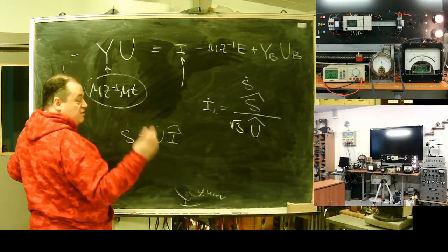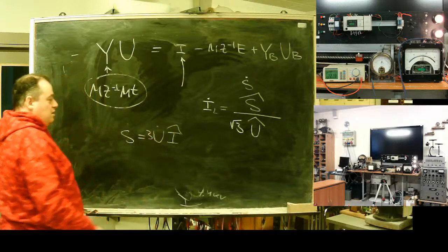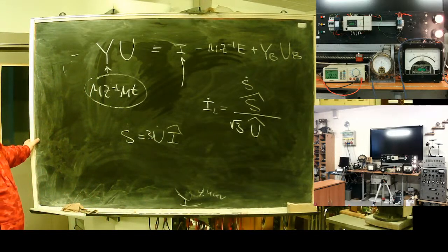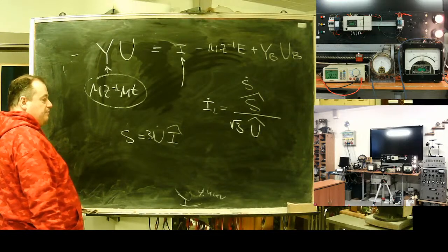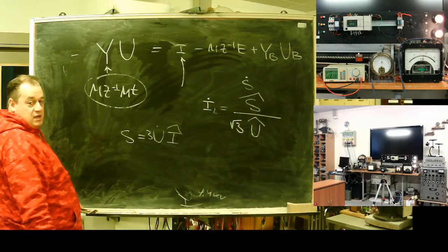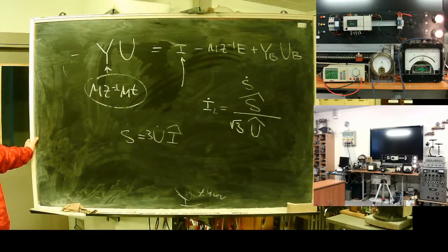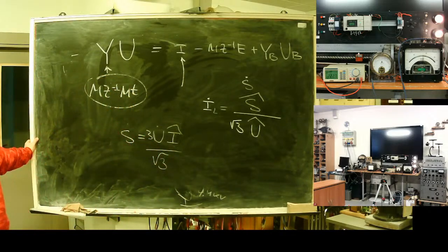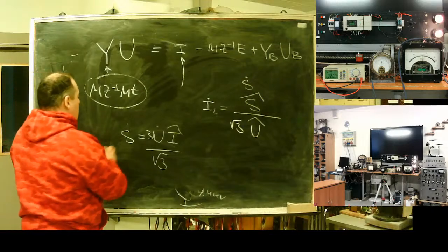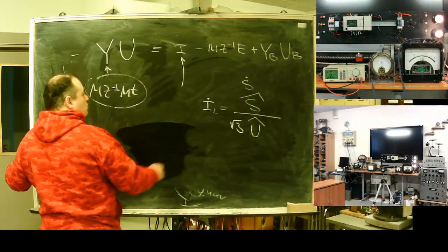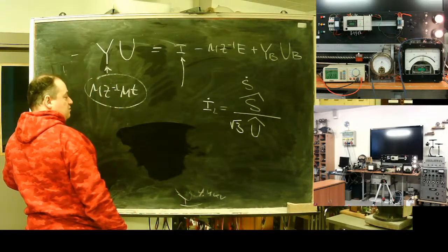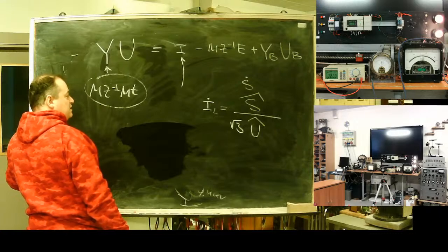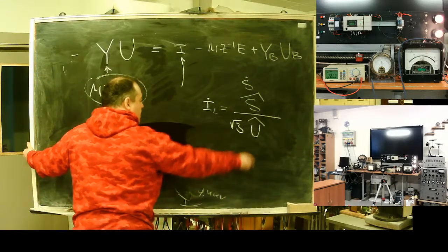But we have a three-phase network, that's why a factor of 3 should arrive. And one moment, traditionally, in such type of calculus, line-to-line voltage is used. That's why it should be square root from 3 to go to phase voltage. That's why load current is conjugated load power divided by square root from 3 and voltage.